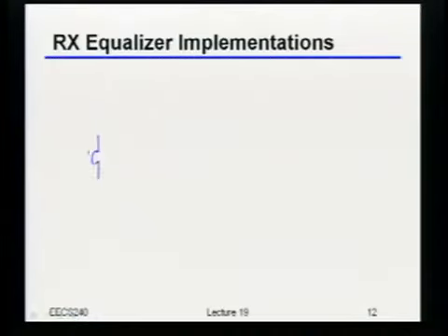So let's say I take my differential amplifier. Normally when we draw differential amplifiers, we draw them with the tails shorted together. But if I wanted to build source degeneration, I could split those two tails into two different pieces. And so now, I still want some gain at DC, right? So what I do is I put some resistance across those two points. Let's call that RS, okay?